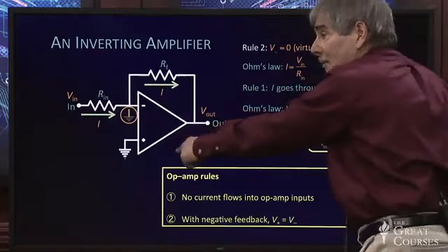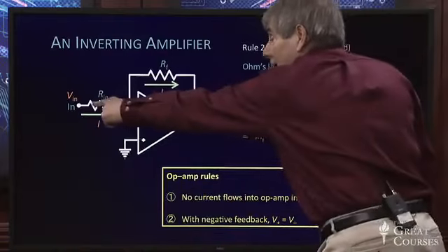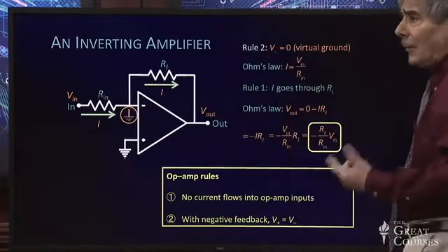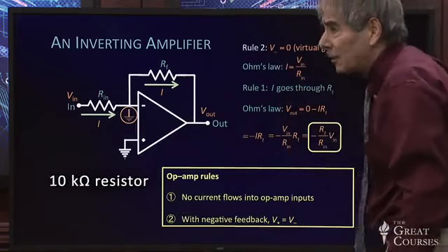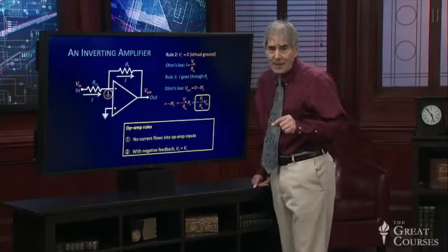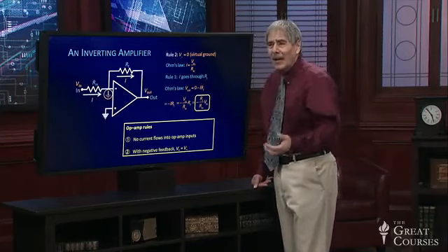Well, the op-amp does, but this whole circuit is the amplifier we've now built. And in this configuration, there's typically significant current flowing at the input. We had a 10 kilo ohm resistor there, for example, in the circuit we built in the previous lecture. So one disadvantage of this circuit is that it doesn't really provide very, very high input resistances.